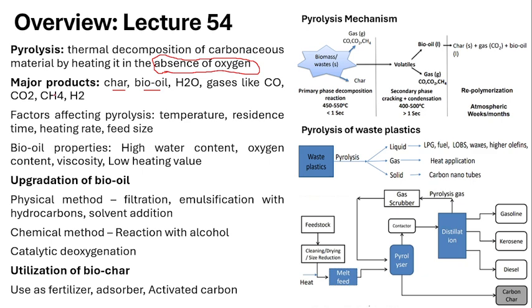Next, as we discussed, one of the main products formed in pyrolysis, which is not produced much in gasification, is the bio oil. However, when we compare the bio oil formed in pyrolysis with diesel, it will have a higher water content. It will also have a high oxygen content, and the viscosity will be higher, but it has a low heating value. Since the presence of water is higher in it, the heating value of this bio oil is very low.